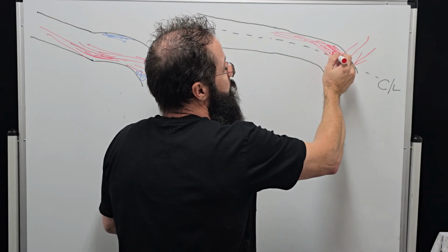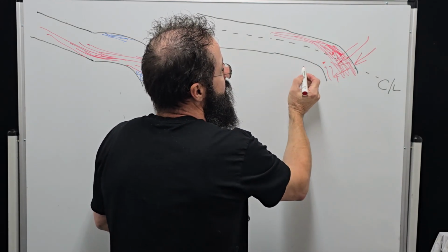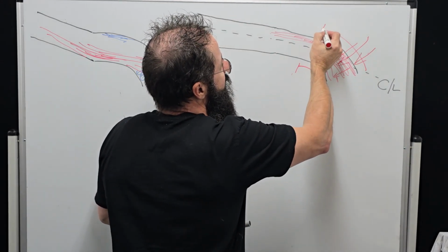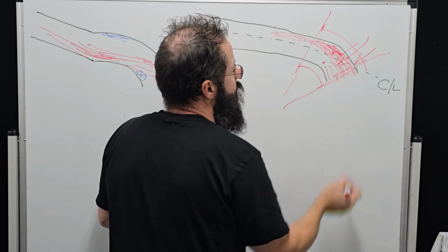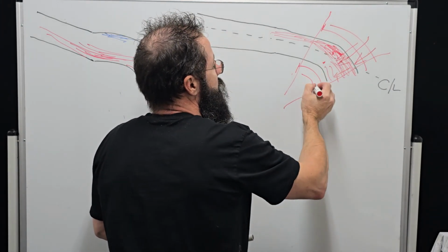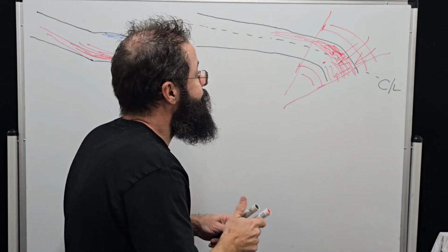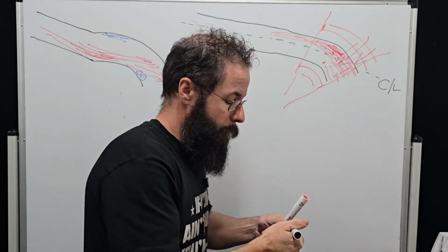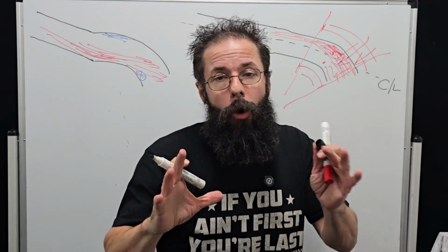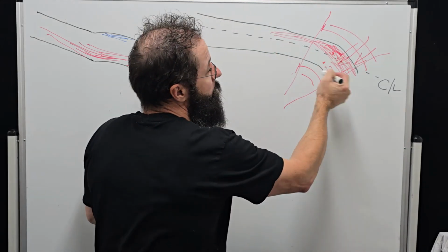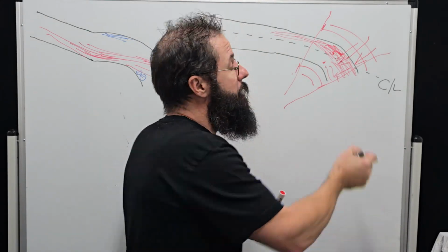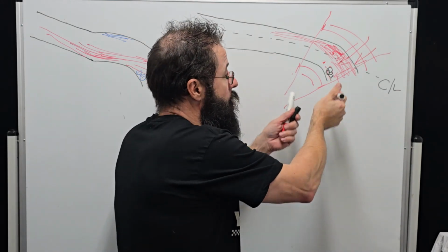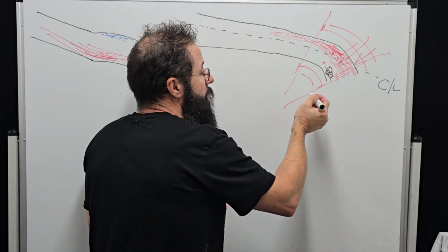meaning the air up here needs to be a little faster than the air up here, because if we look at the distance that has to cover versus the distance that has to cover for the same arc ratio, you'll see that distance is greater than that distance. This should be obvious. So this is where that shaping, that diagram I just showed, comes into it. And this is why we don't want a round mandrel, because a round mandrel means all the velocity is the same, hence why we lose pressure here and we create separation, turbulence, and reduce that cross-sectional area in the bend.